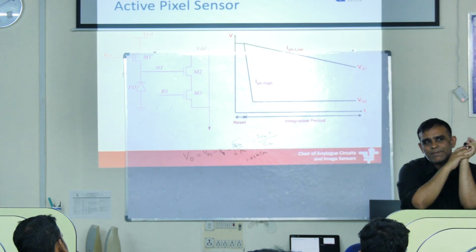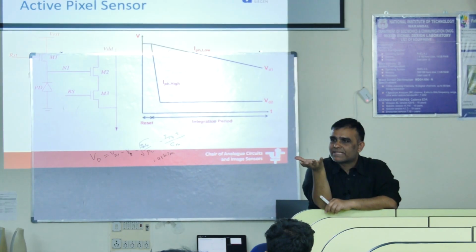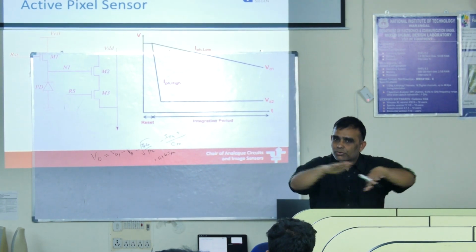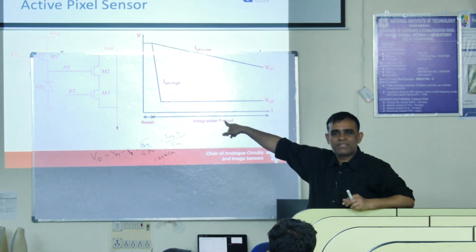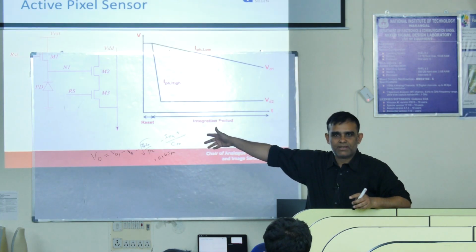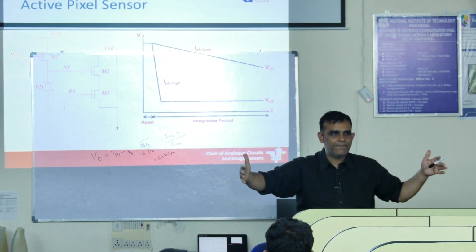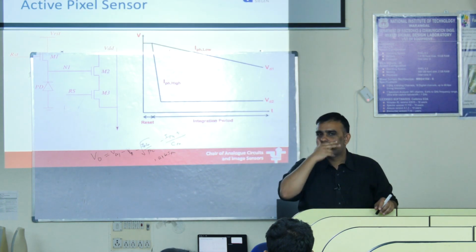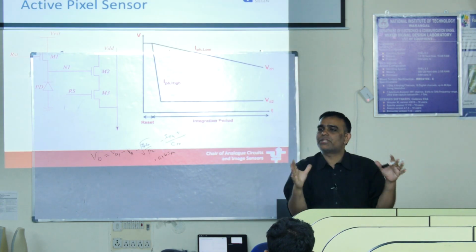In order to make each pixel small, inside the pixel, what do I want to be the biggest? The one which is capturing light. Remember, it's a 2D structure, so the diode and transistors all have to fit, and the diode is the only thing capturing light there. So I want my diode to be as big as possible. We have a number which tells the ratio of the diode versus the total pixel.